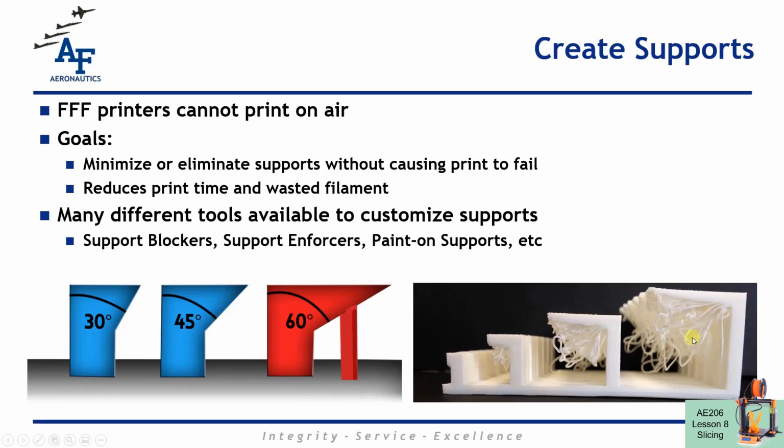And eventually there's enough in this rat's nest that it starts to support the layers on top, and eventually you'll start to have these layers that are the correct geometry. But all of the unsupported initial layers underneath this 90-degree overhang are just absolute trash, and the original geometry did not print at all. So this is an area where we would definitely need supports with the 90-degree overhang.